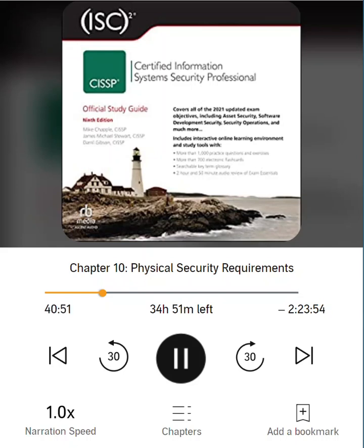If the system loses power, the detection and alarm mechanisms will not function. Thus, a reliable detection and alarm system has a battery backup with enough stored power for at least 24 hours of operation. If communication lines are cut, an alarm may not function, and security personnel and emergency services will not be notified.